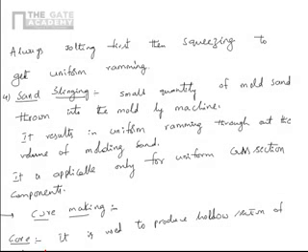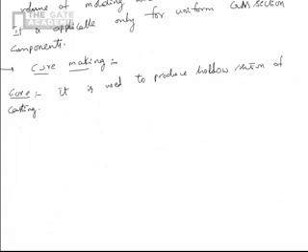What we need to do is insert this core inside the cylindrical surface of the cylinder, which helps us to produce a hollow casting. The core is also made with sand only. CO2 molding is used to prepare the core.